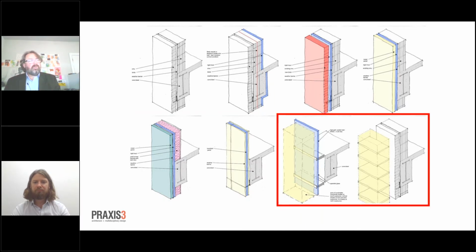So we looked at what we were doing for the curtain walls on the north and south face, where we have glass, and we were getting considerable solar gain and a lot of radiation coming through the wall. We introduced those yellow boxes, which were areas where we were going to have sunshades to protect the glazing from direct light, that radiation and so forth. And we asked ourselves, what if we could do something like that in front of the brick? Would just doing that improve its performance? And the answer was yes, it would, but it would be a pretty complex thing to do.